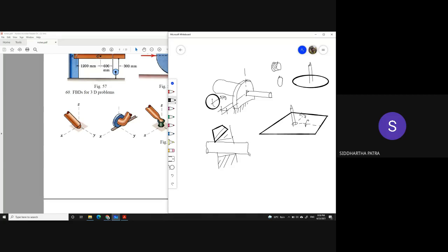Now, obviously, I'm showing the clearance in quite an exaggerated way. That much clearance would probably not be there. But do you see the picture that if I make this thinner, the constraint is lower, and if I make this wider, the constraint on rotation would be higher? I just took a section along an XY plane of the joint right there. Does this picture make a little sense to you?